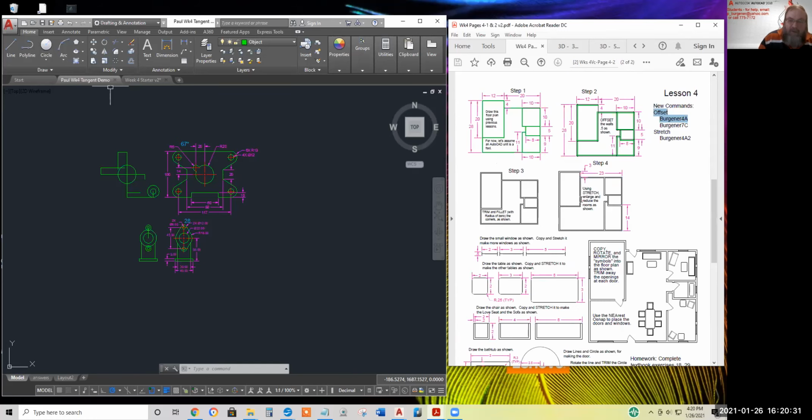But hopefully I'll remember to demonstrate if you rotate this little condo floor plan, the offset command will make parallel copies of diagonal lines, which is very time consuming using drawing some construction lines and using object snaps and copying it along a